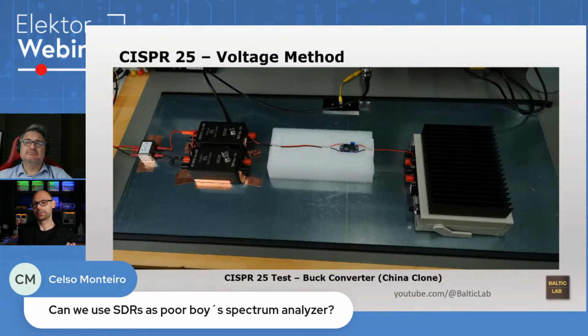The next thing is, a traditional spectrum analyzer actually does sweep through the spectrum continuously. A CISPR-compliant receiver would step through the frequency band with a distance of half the resolution bandwidth. This is also something that's difficult to set up with cheap equipment. So yes, you can use an SDR, but you need to really watch a lot of small, intricate details, which can be found on the internet. But you're going to have to implement them on your own.